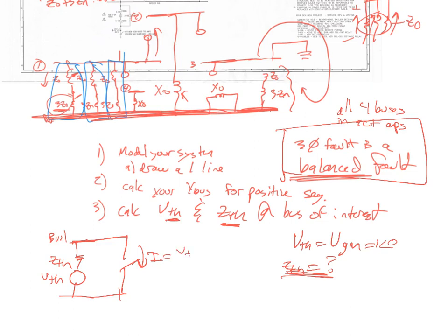To me, it's V Thevenin over Z Thevenin. Last time I asked Mr. Ohm, or Sir Ohm, or whatever he was. So the statement about just adding impedances was wrong. Adding impedances is incorrect. It's a good guess, but it's not right. You have to go through and see what's in parallel and what's in series, and analyze the whole circuit.